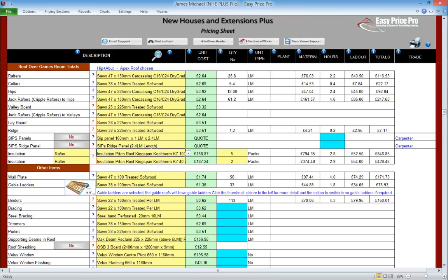OK, so as we have seen, the totals for each roof section that is entered are dealt with independently, meaning we can fine-tune the details of the timbers, any SIP panels, and insulation really easily, and ensure that each individual section of roof is set to our exact preferences.